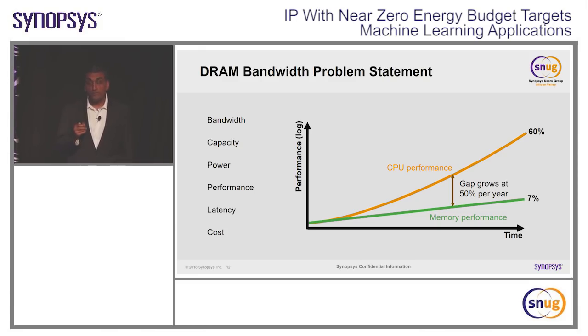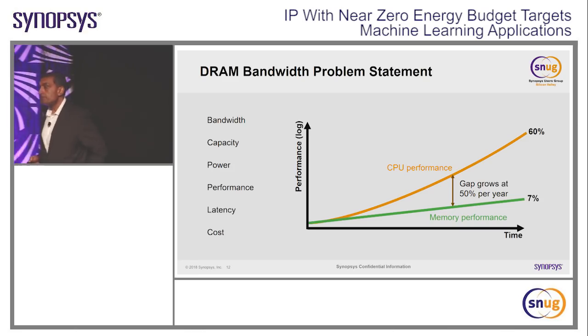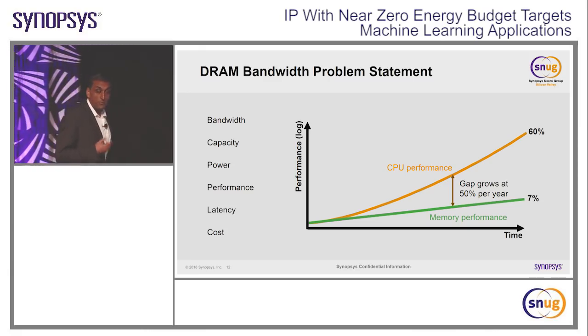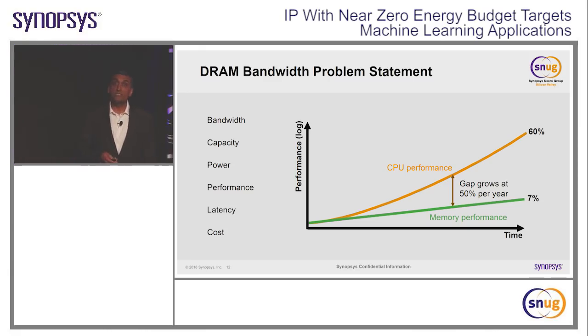The DDR performance, the DDR is the technology that connects to the DRAM, is limited in its nature because it's a parallel interface and it's a non-embedded clock. DDR4 is moving to DDR5 for servers. In terms of the edge devices, the implementation is low-power DDR, and that's moving to LPDDR5. And there's also a concept in this parallel world of graphics DDR. GDDR5 is moving to GDDR6. Okay? So the key points to absorb as we're going through this presentation are really the bandwidth, the capacity, and the power. And we'll do that in relation to the performance and the latency as it interfaces to a high-speed memory.